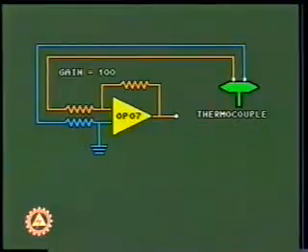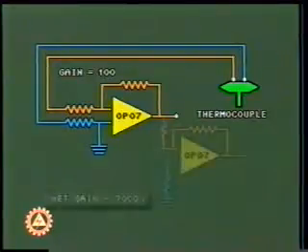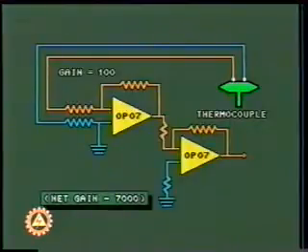The amplifier circuit comprises OP07 operational amplifiers. The first operational amplifier provides a gain of 100, while the second provides a gain of 70. Therefore, the total gain provided to the sensor output is 7000. The amplified sensor output is now compatible with the voltage level required by analog to digital converters.